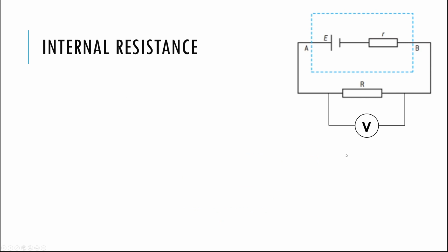All right, remember the process with Kirchhoff's law. We want to first draw our current. Now this is a simple one, it's just one loop, so I'm pretty sure current's flowing this way. Although honestly, if you guessed the other way, it would totally work out for you. But the current is flowing in this direction for sure. Next step is I want to label my pluses and minuses. So remember our rules here. Let's go green.